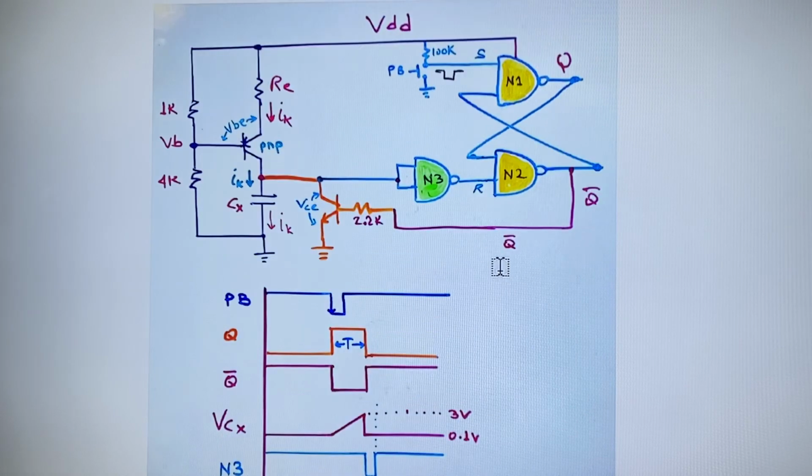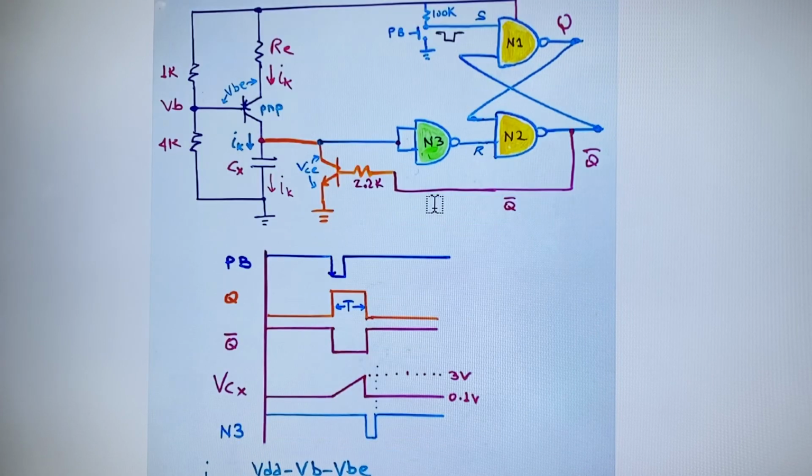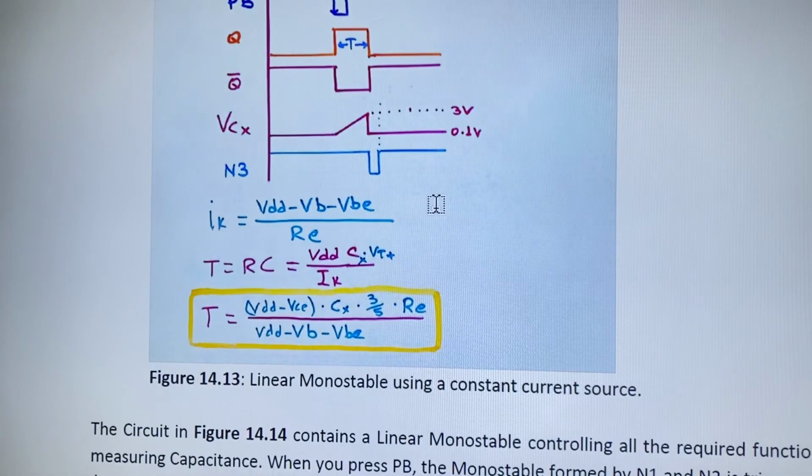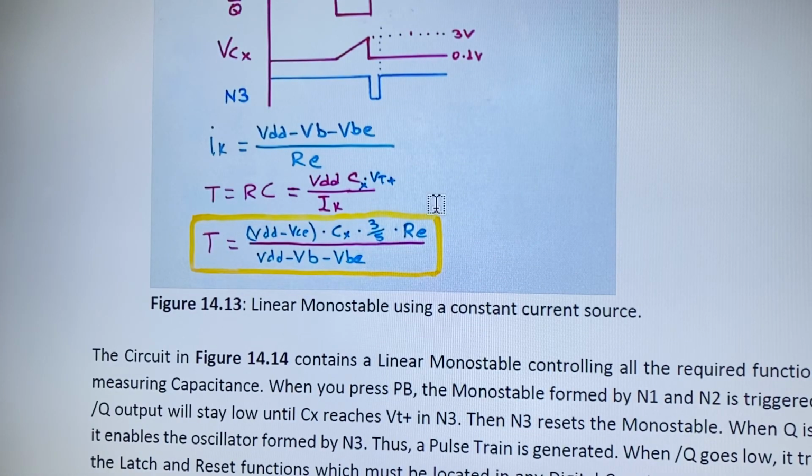So it is a good experiment for the student to test it, and that way you prove that the NAND gate has a positive threshold voltage. It might vary depending on the brand of the technology that you're using here. It might be a 4093 or HC132, and it also depends on the temperature. You have to check the data sheet to determine at what temperature you are testing this circuit.